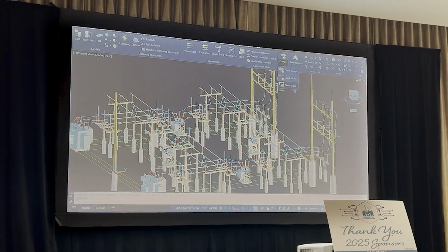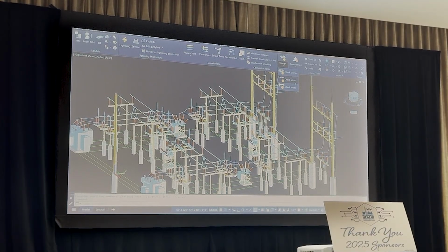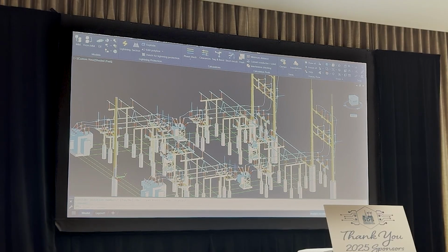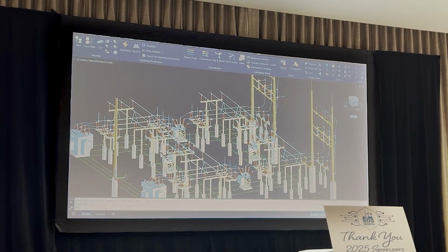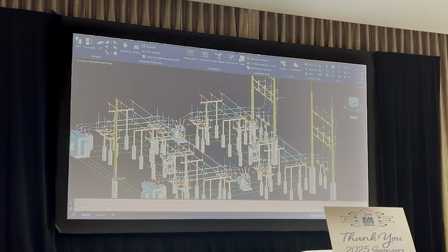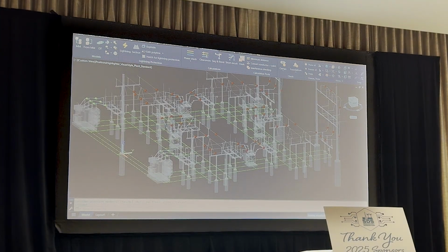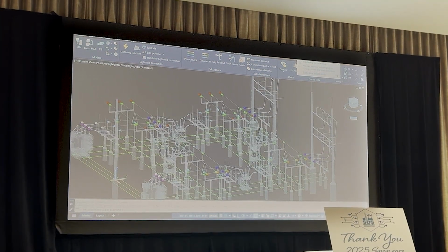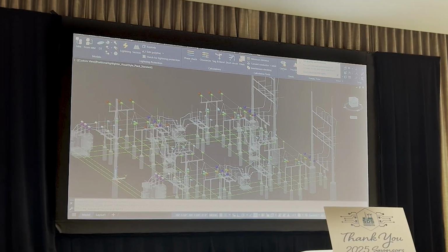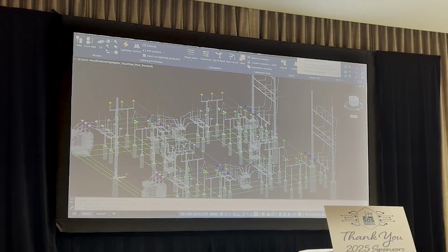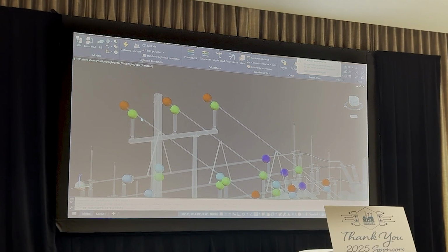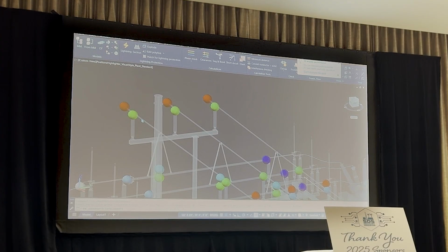There's also one for clamps and one for tubes. The one for clamps is a little more useful than that one, I find. So this one's going to run. And what it's doing is it's looking across all these fittings, whether I put them in physically and actually snap it to something, or even if I just put a virtual thing there, it's counting it, right? So if you look out to the end of these bus runs, you remember I had bus clamps to the end of here, and I said I'm going to throw some end bells, but I'm not going to place an end bell. It's just an end bell.